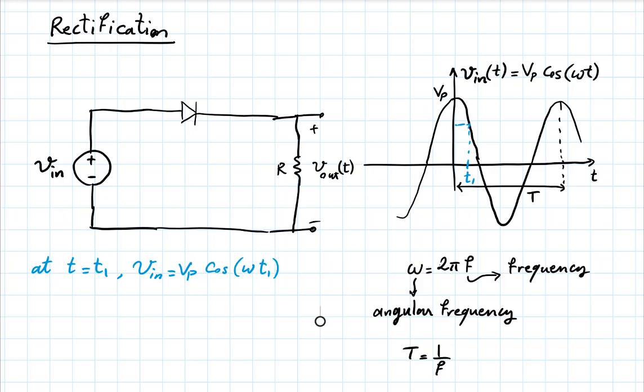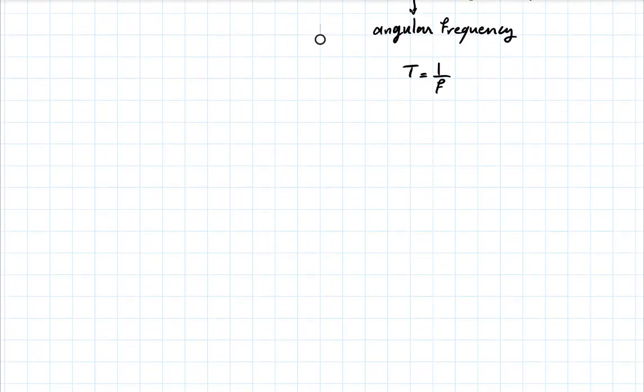Either the diode is on, which means there's no voltage drop across it, but it can allow any positive current, like the lines that I just drew on the characteristics that I just showed you, or it's off, which means it has a negative voltage across it, but there's no current going through, right? So if I have a positive V in applied to it, let's say 3 volts, in this circuit, and this is just a simple resistor, would the diode be on or off?